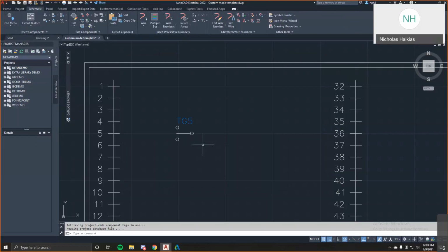Okay, and I'm just going to show you how to do this. So I'm going to type in scale. I'm going to use the scale tool, select the switch, and press enter. You can just click a point, and then I'm going to put in a scale factor of 2, and now it's twice as big. That's just how you would do that.